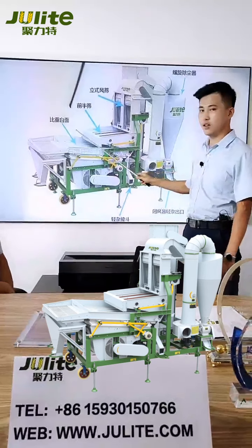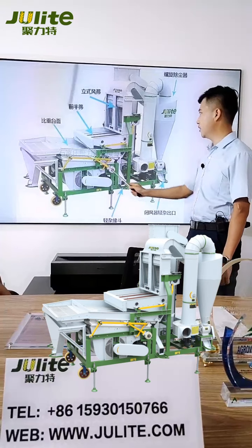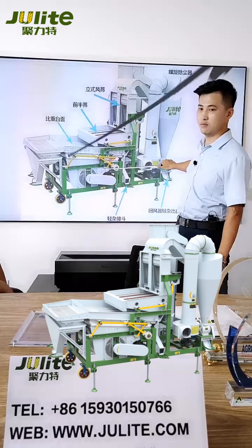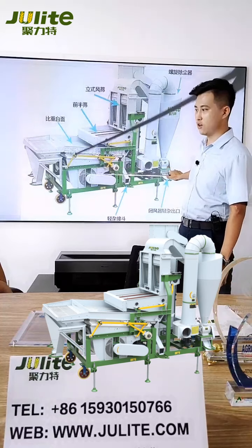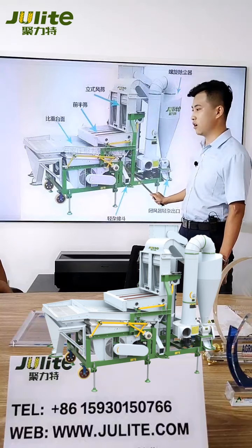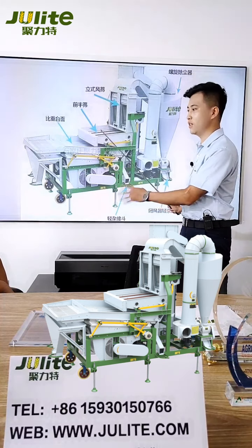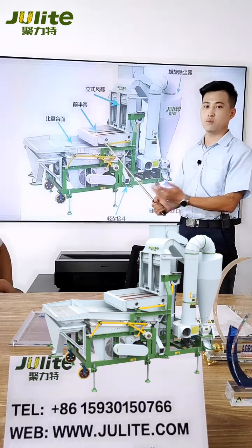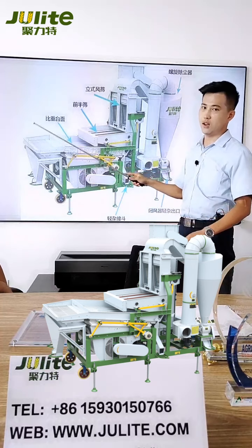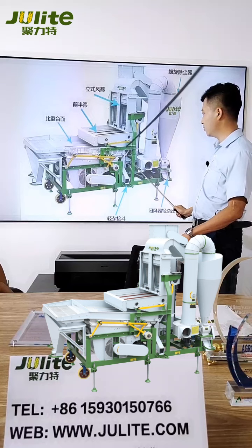After this is a gravity table. Here this part is the gravity table, and in the bottom is a blower to blow the air from the bottom to the top. We know because of the gravity, the grains on the surface of the gravity table, and the good materials will go back to the outlet, and the lead impurities will go down to this place.